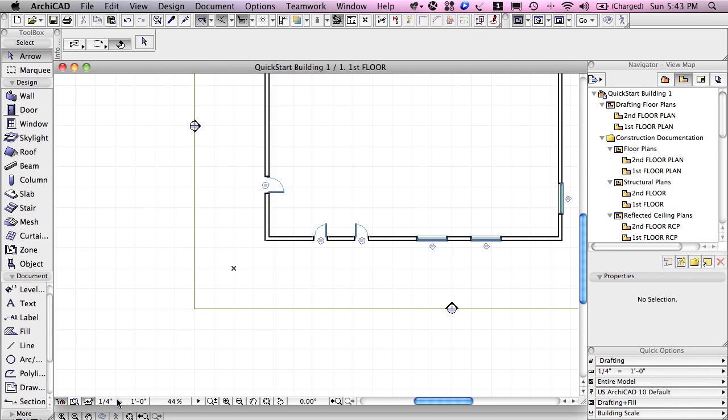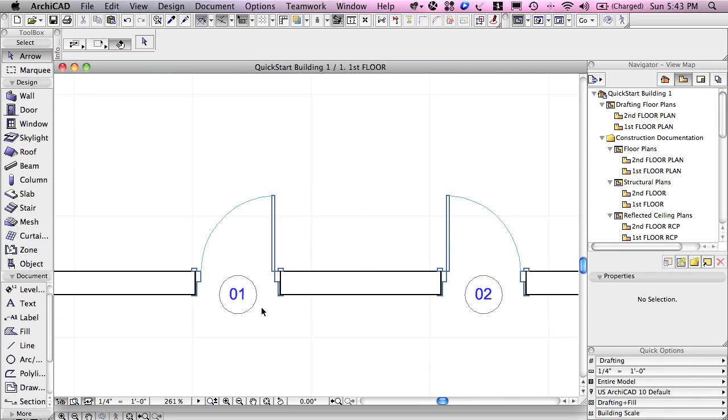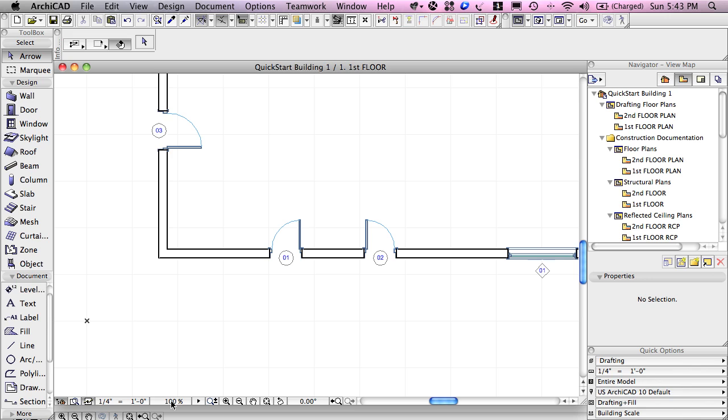Now these percentages are related to the paper size that this drawing is set up for, and the paper scale is set up to allow you to see the size of text and other markers in relationship to the building elements, because obviously these walls are internally represented based on their size in the real world. I think this was 60 feet long is what I had, which would be about 20 meters. But the information in terms of the markers, for example, the door and window markers, and this is just one style, but the size of the text and the size of the circles or other markers are based on the printing scale. So we'll be looking at that, of course, in much more detail later. But if I click on this %, this puts it approximately at the real-world size of the paper printing when it's at 1/4 inch, which would be about 1:50.